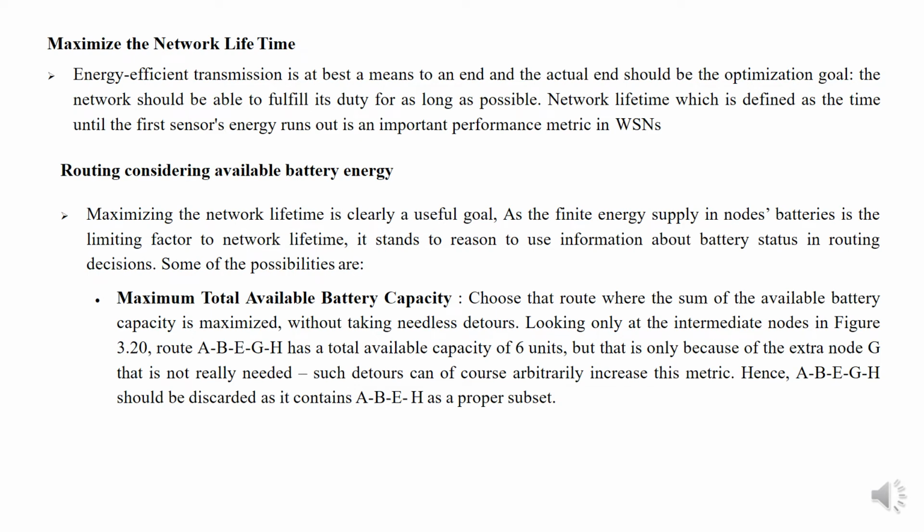Routing considering available battery energy: maximizing the network lifetime is clearly a useful goal, as the finite energy supply in the nodes' batteries is the limiting factor to network lifetime. It stands to reason to use information about battery status in routing decisions.